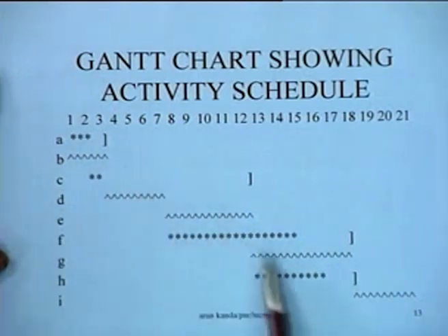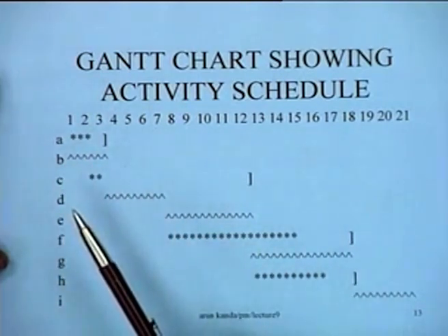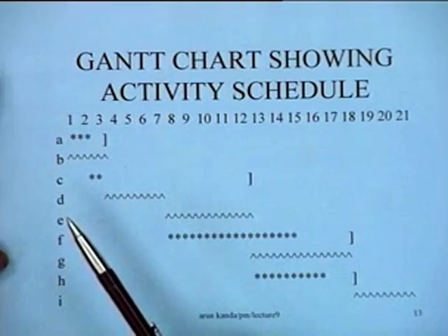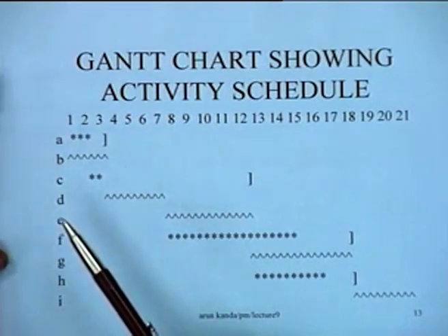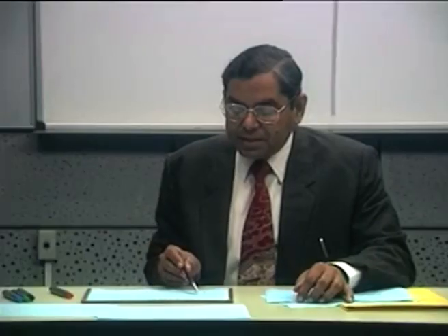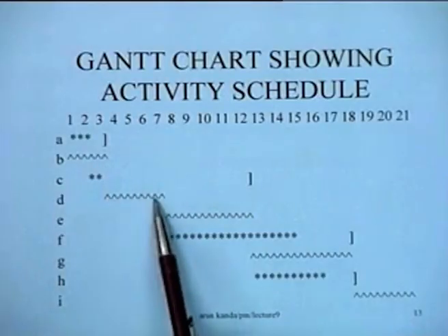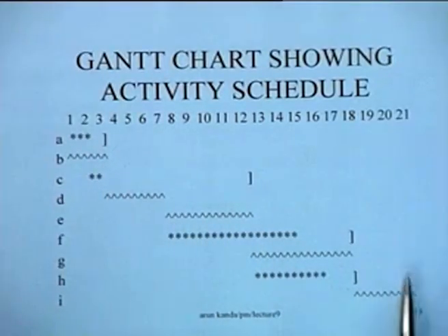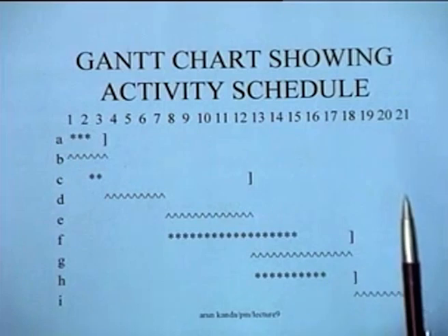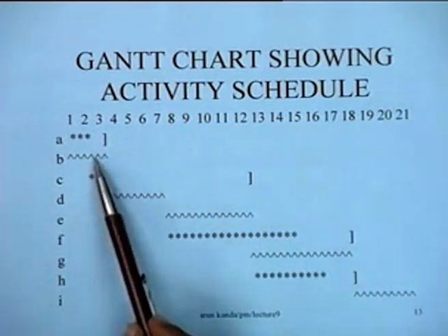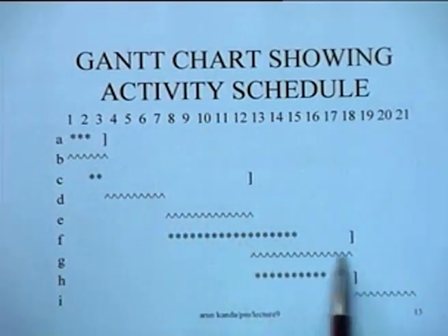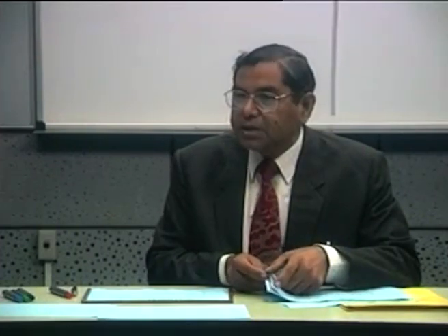So this gives you a timetable and also shows you the kind of flexibility which is available when you have to implement the project. You know that the critical activities in this particular situation, all these durations add up to the critical path duration of 21 days. All the critical activities are adding up to the critical path duration of 21 days. I think that's one of the interesting things, that that's an interpretation in fact of the critical path.